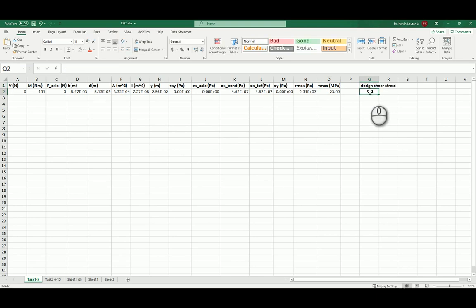Right, so based on your material properties, what is our design stress? So that is what you have gotten from MATLAB, right? And you're using the tau max, so therefore it is maximum shear stress theory. So it is what? Sigma yield on 2n, right? We know that n is 1, because it said in the script that your factor of safety is 1.